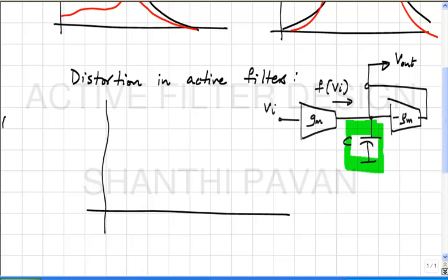Now if this current is not going through the capacitor, where must it be going? It must be going here, right? So what must the equation governing this node voltage to this current be? If we apply the nonlinear relation to this transconductor, then f of Vout must be equal to whatever I is flowing there, correct? Because it's the same kind of transconductor, right? The sign reversal has already been accounted for in the sign reversal of I. Please note that I is flowing into the transconductor now.